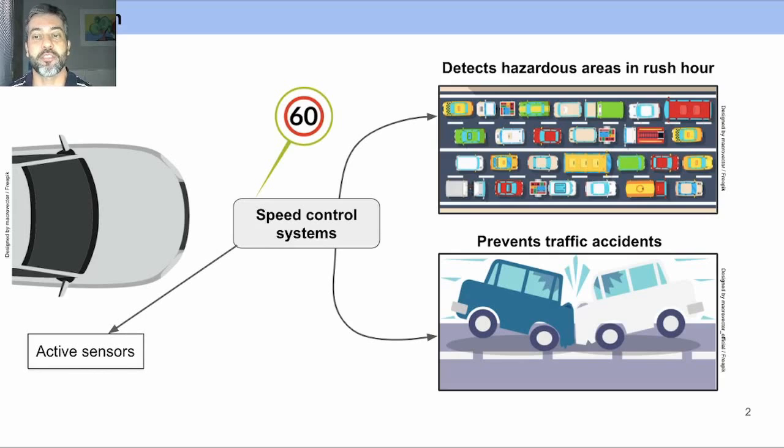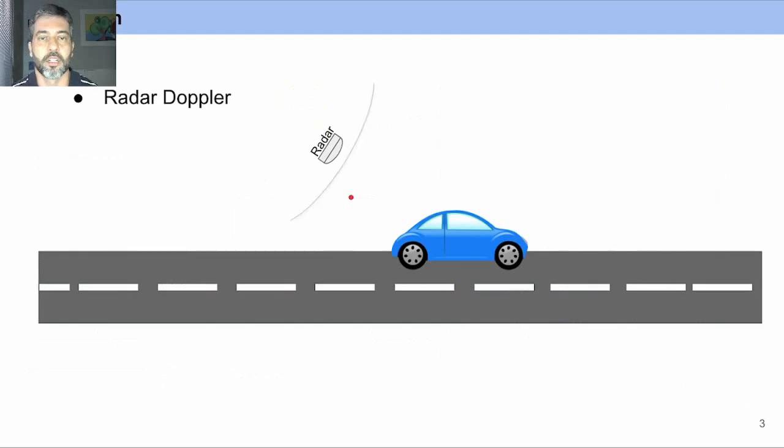Active, which measures the effect of signals transmitted to a vehicle passing on a highway, and passive, which comprises video systems whose analysis of consecutive video frames serve to track a vehicle and thereby measure its speed. For active systems such as radar, sensors that perform speed measurement are used to trigger a video camera to record plates of the vehicles. This active device emits a continuous radio signal wave, captures its reflection and calculates the speed. It works based on the analysis of the wave that was emitted.